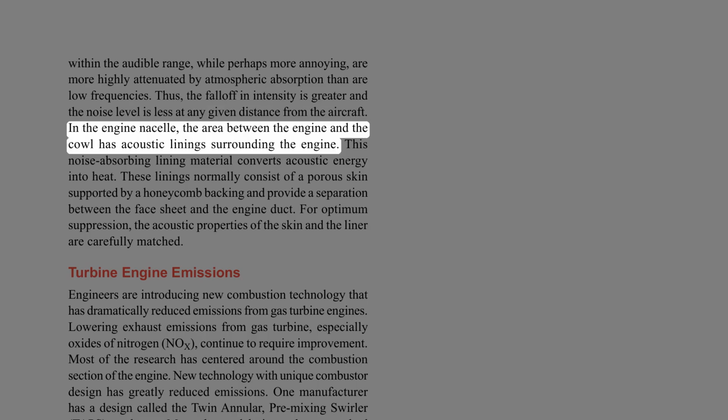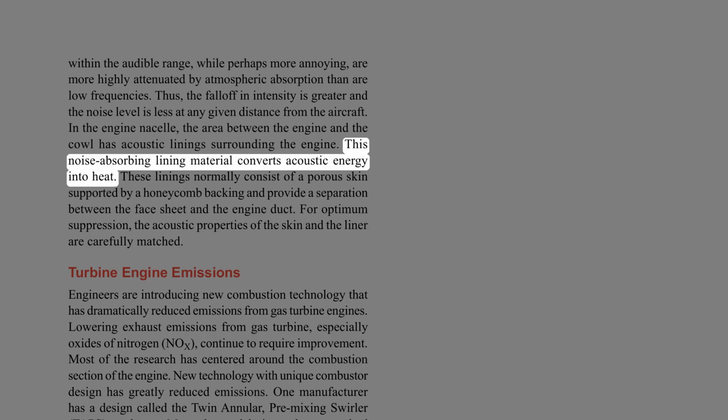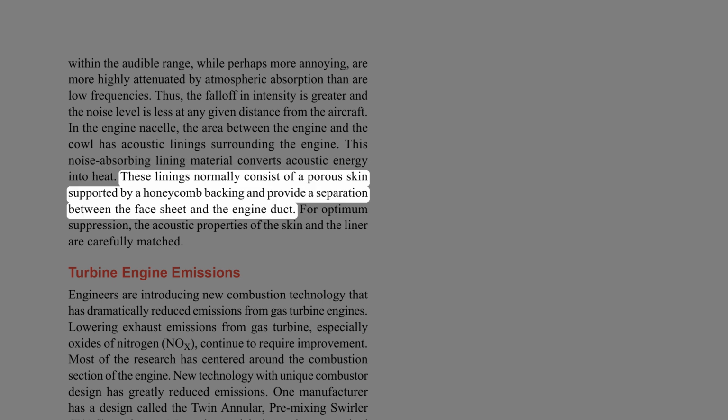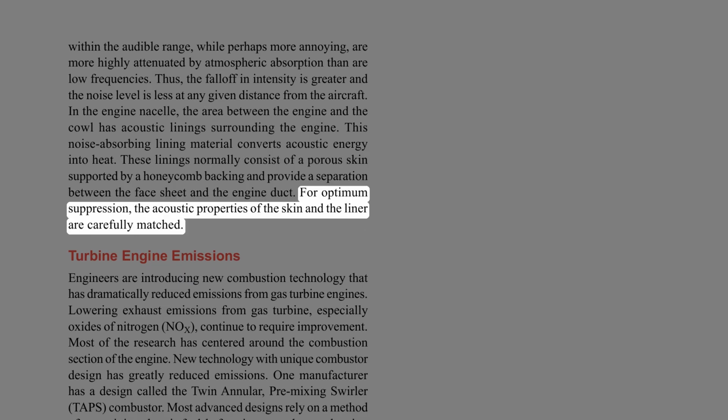In the engine nacelle, the area between the engine and the cowl has acoustic linings surrounding the engine. This noise-absorbing lining material converts acoustic energy into heat. These linings normally consist of a porous skin supported by a honeycomb backing and provide a separation between the face sheet and the engine duct. For optimum suppression, the acoustic properties of the skin and the liner are carefully matched.